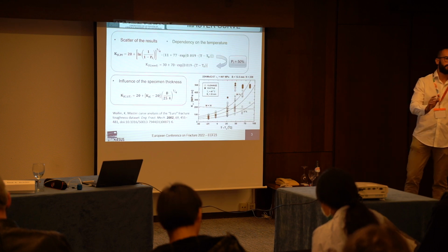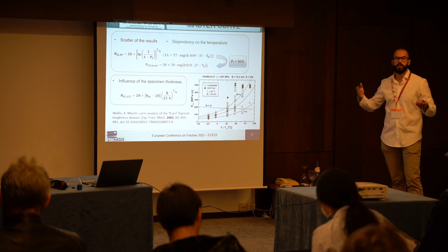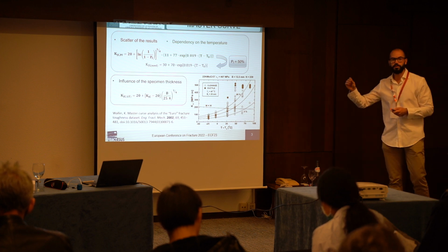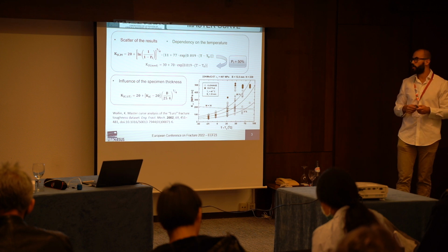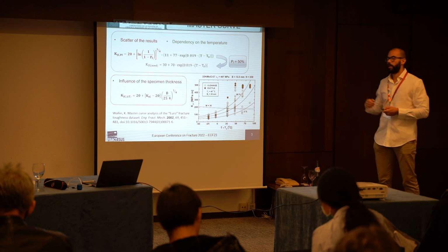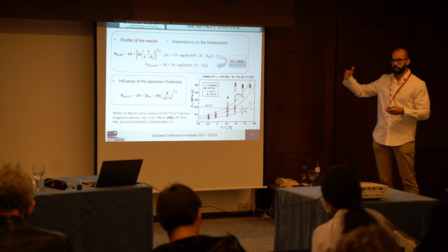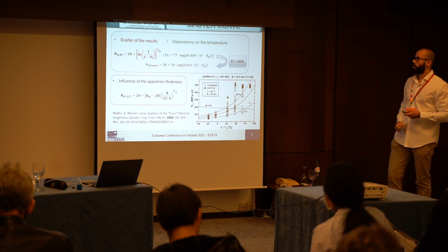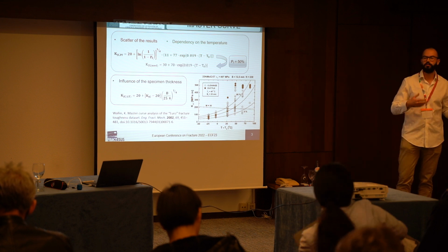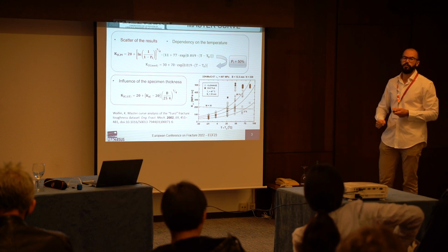Okay, as I briefly introduced before, the master curve approach was originally provided by Wallin. This approach is based on the theory that can be described as a three-parameter Weibull distribution and a single parameter, the reference temperature. So, once you have obtained this reference temperature, you can obtain the master curve for any probability of failure, the most commonly used being the probability of failure of 50%.